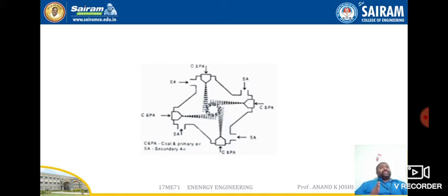Due to the arrangement at the corners of the burner, the adjacent sides of the form created by the tangential burners create swirling. As the flames interact, it leads to this swirling action. So this produces sufficient turbulence in the furnace for complete combustion. Hence in such a burner, there is no need to produce high turbulence within the burners.